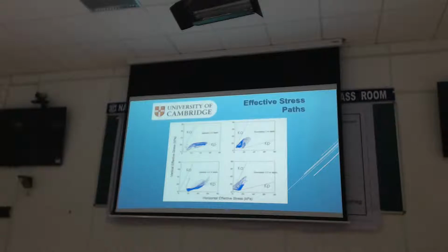Yeah, we're not talking about forces here. These are stresses trying to pull on the pile, which will be proportional to the suction it seeks. So if I get the suction, this will say I got more stress. We're only looking at stresses, right? We're not linking this to strains yet. So it is right. I haven't done any manipulation. I just plotted the same data for both. All I'm saying is, look, even downslope, there is part of it close to Kp, which has to be true. It's not in contradiction with the fact that more soil moves on the top.